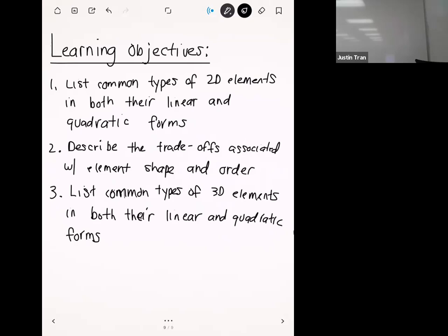Are you expecting, let's say, varying loads, like varying housing loads? Do you expect us to apply a torsional load? If it's appropriate, yeah. If it's applying a torsional load, it's not that difficult. We've only done force and pressure loads, but torsional loads work the same way. You just click on the surface and you apply a torque on that surface. Other people have asked me the same thing, so if you think that it's appropriate, then that's definitely fine.